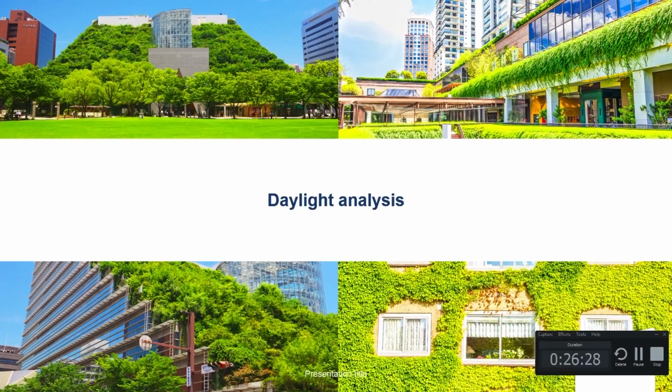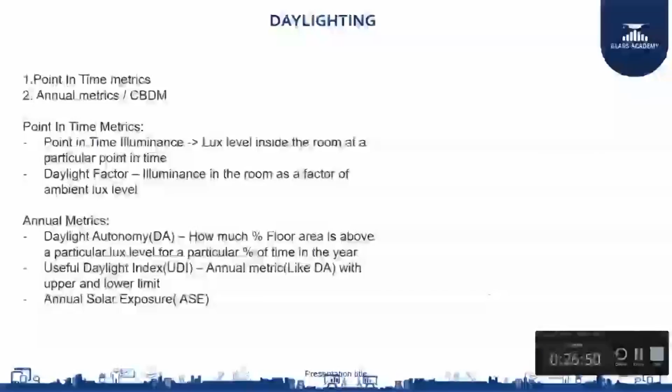Daylighting analysis. So we have considered the geometric design aspect in the sun path by studying the shading, etc. And we also know the impact of glass on your energy savings by using your whole building simulation. Next comes your visual comfort, where you need to have natural daylight enter into your building through the openings in your building envelope.